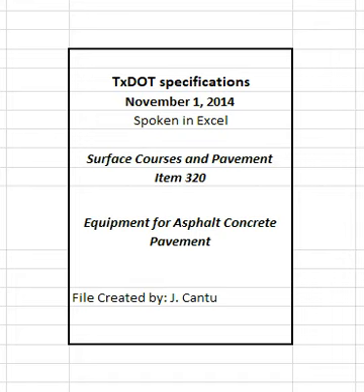2.1.3.2 Surge bins. Provide one or more bins large enough to produce one complete batch of mixture. 2.2 Hauling equipment. Provide trucks with enclosed sides to prevent asphalt mixture loss. Cover each load of mixture with waterproof tarpaulins when shown on the plans or required by the engineer.